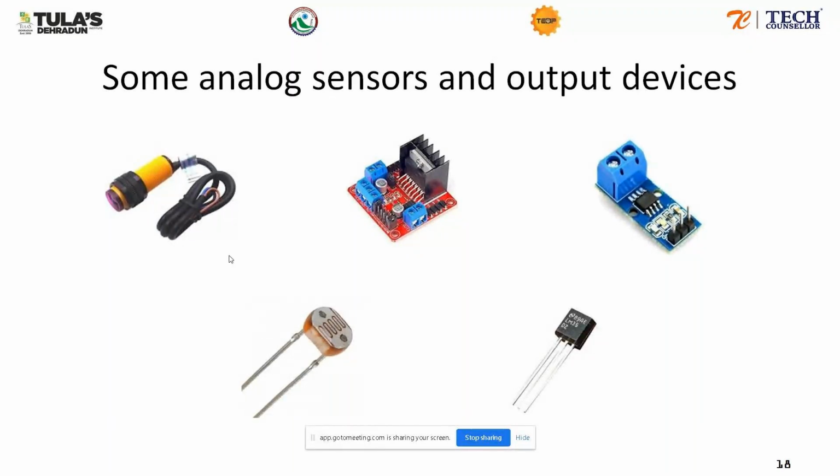Well, what is done is, instead of it returning just a digital output of 5 volts, it gives you a value between 0 and 5. So if there is no one there, it will give you 0. If there is someone at 90 centimeters, maybe it will give you a value around 0.5 volts.